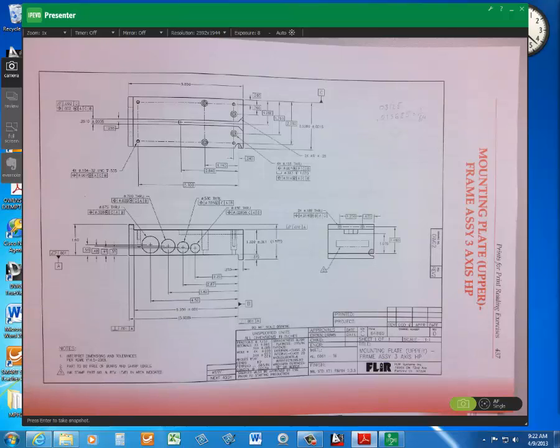So starting at the smallest for the hole, 0.187, your position tolerance would be what? It's right next to the circle M. Your positional tolerance for the smallest hole of 0.187 will be, since it's circle M, okay, there's no math required.